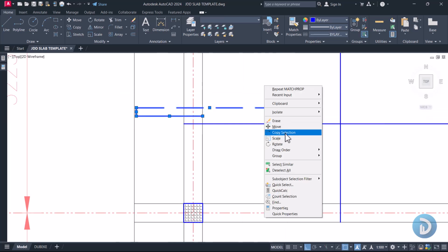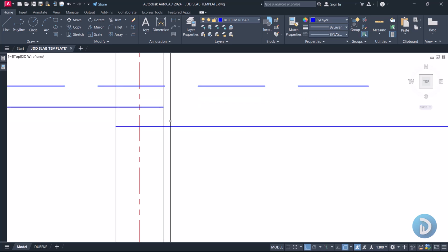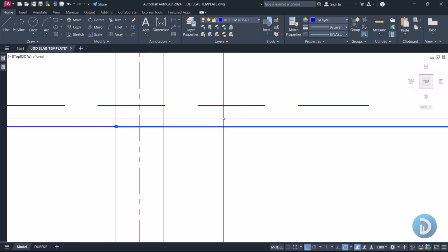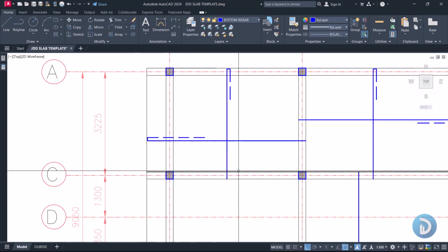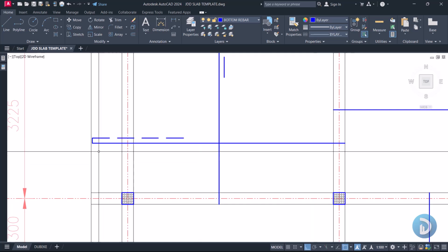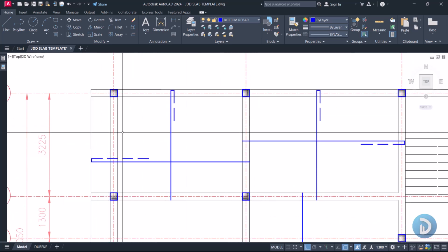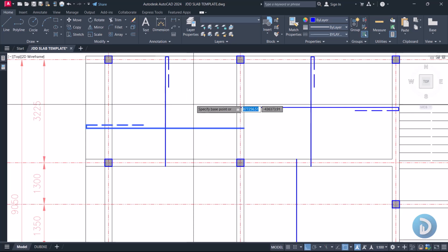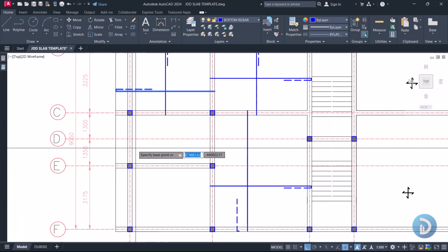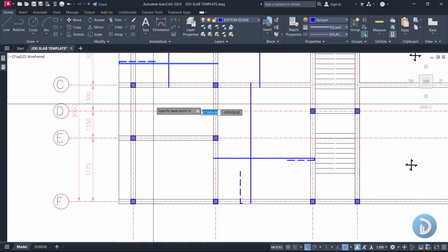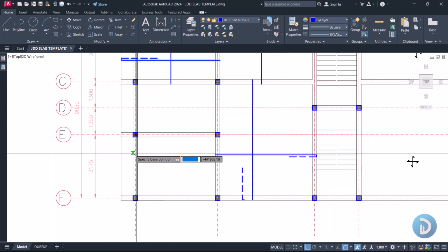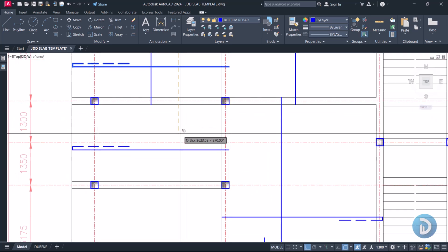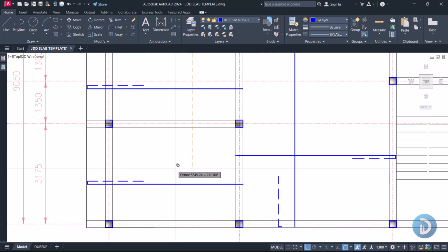and do not forget that we can merge this reinforcement together. Okay, so this will be something like this. Okay, so now we have our reinforcements, and this is how to deal with your cantilevered edges. And as you know, this same cantilevered arrangement, we also have on this other part, because they have the same width of the cantilever. So we can copy this reinforcement from here up towards this part, and we can also copy this reinforcement from there to this part.